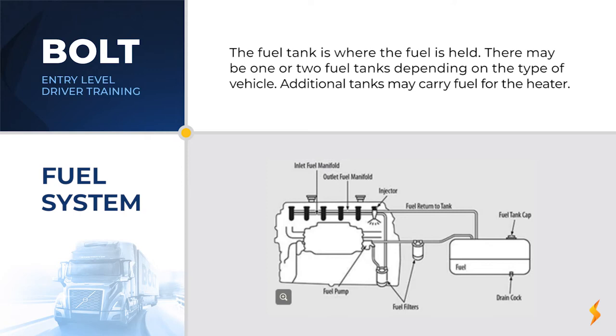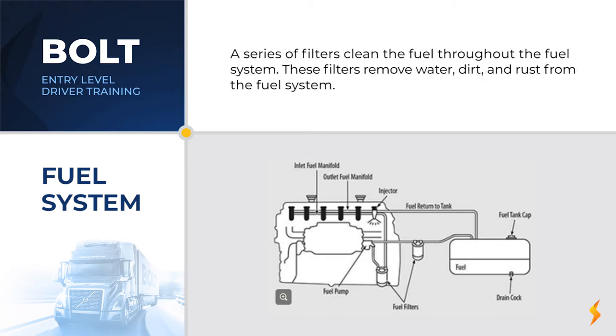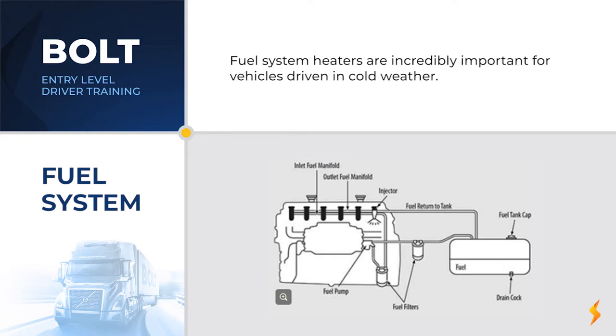There may be 1 or 2 fuel tanks depending on the size and type of vehicle. Additional tanks may carry fuel for heaters and reefers. A series of filters clean the fuel throughout the fuel system. These filters remove dirt, water, and rust from the fuel system. Fuel system heaters are especially important for vehicles operated in cold weather.